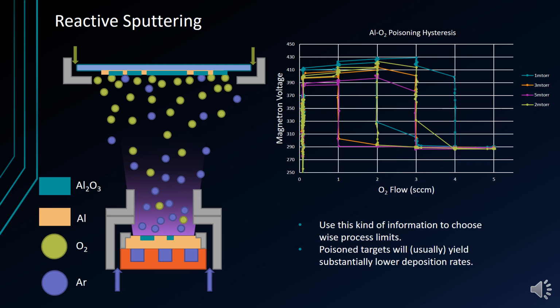This helps to produce a higher argon to O2 ratio at the target surface, and a higher O2 to argon ratio at the substrate. The reactive gas which reaches the target surface may form islands of reacted compounds. If the material is a dielectric or is much harder to sputter than the pure metal, then the sputtering rate can drop substantially. This is known as target poisoning, and it can be reduced by plumbing the gases in separately so that the reaction takes place primarily at the substrate.